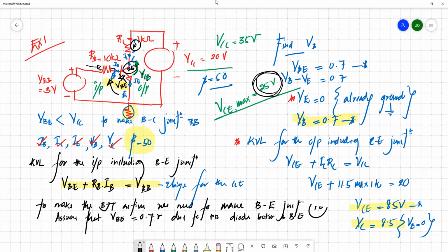So you can decide a lot of things by going through the data sheet. What would be the supply voltages? What would be the biasing level? Where can we place this transistor? What's the impact of temperature and how do we manage it? For certain transistors, we have to manage the temperature, and sometimes you may need a heat sink to regulate it. So there may be a lot of issues. For the heat sink, you have to design it by looking at what kind of heat is generated by this transistor. You have to transfer this heat from the transistor to the heat sink. So likewise, you can get a lot of information by going through this data sheet. But these are very simple information you can pick, other than this beta value.